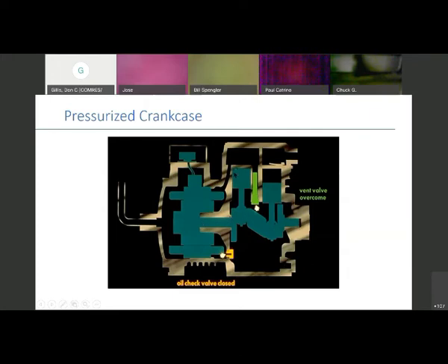When we start to get that oil loss and that blow-by, our less pressurized side of the crankcase, 2 pounds, 3 pounds, 4 pounds, whatever that looks like, starts to pressurize. This vent, by the way, is put in here to keep the pressure lower on this side. When that vapor comes across this motor and cools it, it comes across this throat and across that vent and almost causes a Venturi effect. Think about sucking on a straw as it passes over there. So it's always keeping this pressure lower. Unfortunately, when we get this ring wear and that blow-by, this starts to pressurize. And what happens next?